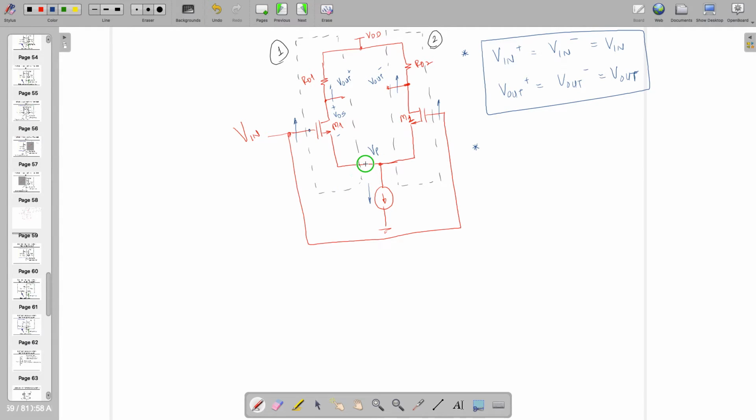If VP is not 0, you cannot say, like in the previous case, that you make it 0 and let's make it pseudo differential, which is acting as a single-ended amplifier. You cannot directly say minus GMRD. So VP is not equal to 0. In that case, it is very important to find out what the resistance is over here. For that, you can just write down RSS for the case of current, because any current mirror you are designing, its output impedance will not be infinite. This is unfortunate, but that is the fact, right?